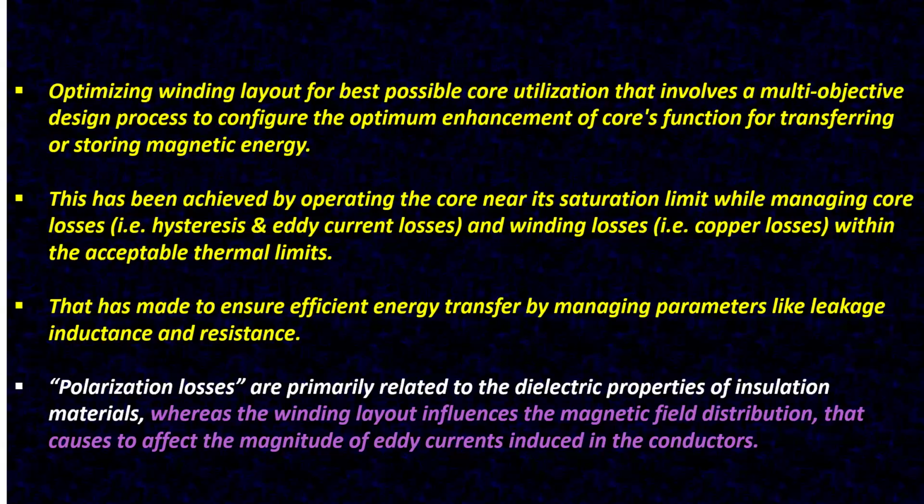Polarization losses are primarily related to the dielectric properties of insulation materials, whereas the winding layout influences the magnetic field distribution, which affects the magnitude of eddy currents induced in the conductors.